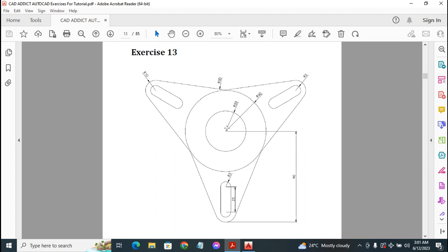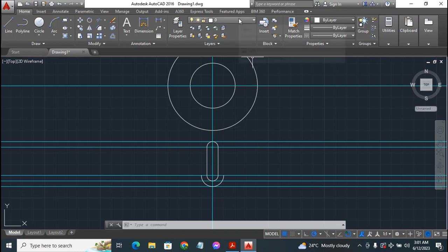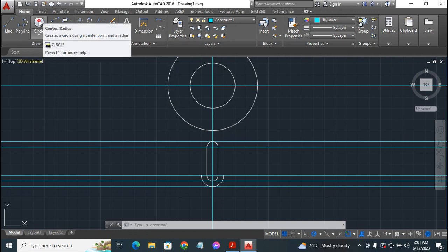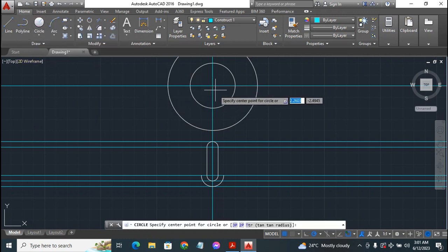Then, let's assume that this circle... let's draw in that circle first. So back to CAD, I'll go back to the construction layer, click on construct one. Now I'll go to draw, click on circle, ensure my cursor locks to the center of this circle. That is not happening. That's because we have some of the options at the object snap deselected.